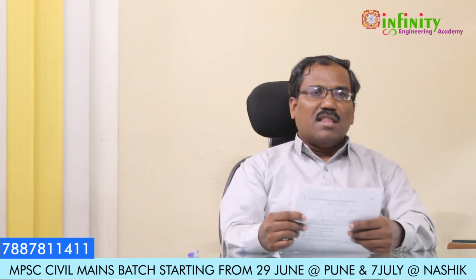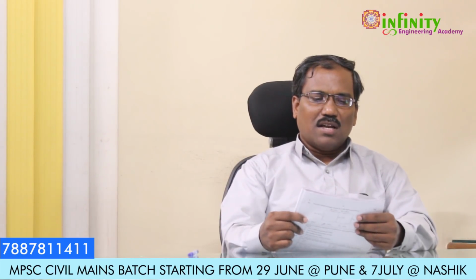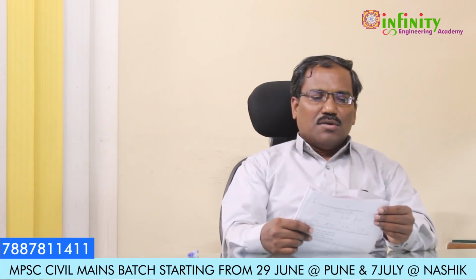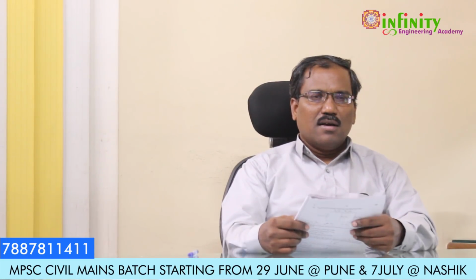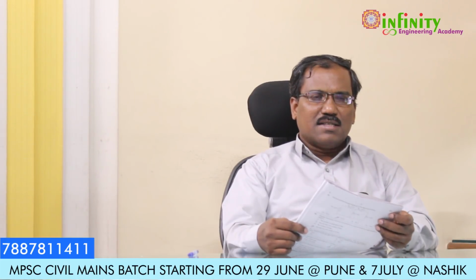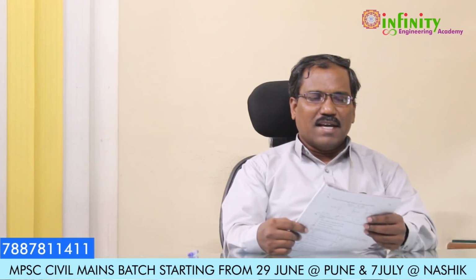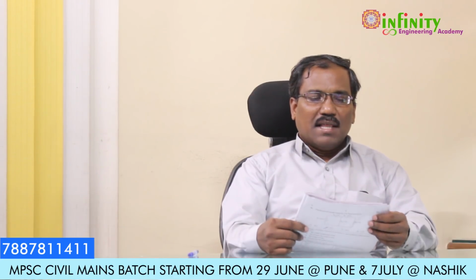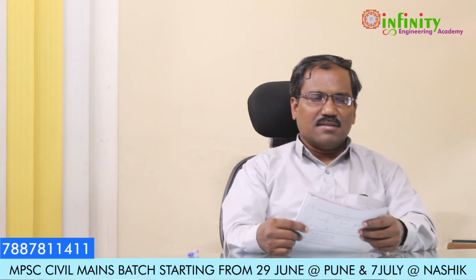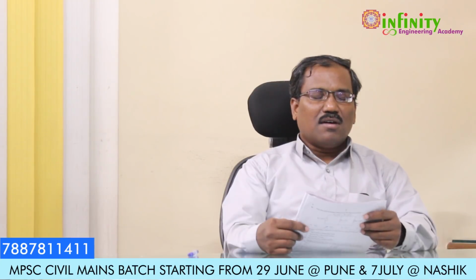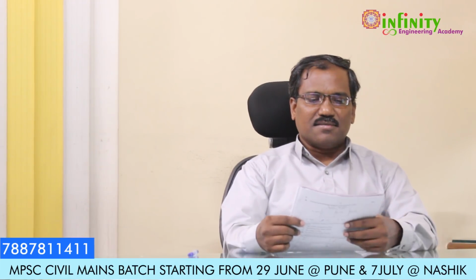And the next one is that in low carbon steels, the presence of small quantities of sulfur improves what? Steel is an alloy of carbon and other alloying elements like sulfur, manganese, vanadium, chromium, etc. In that, the sulfur will improve the machinability of the steels. The machinability is greatly affected by the presence of sulfur in the alloy steels.